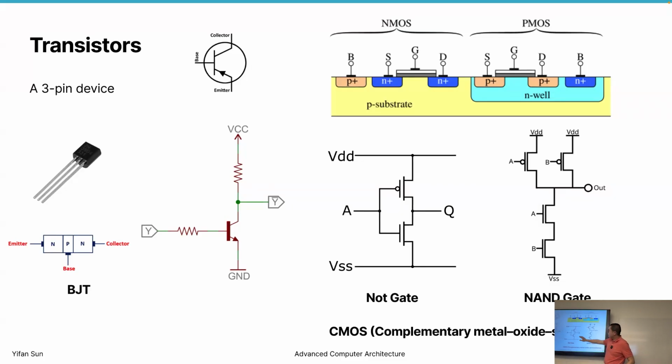So you can consider one side is an NMOS, one side is a PMOS. Don't even need to consider which part is NMOS, which part is PMOS. Just see if there's a circle in terms of circuit annotation. This means kind of a NOT sign. On the input side, that means if it's 0, it's enabled. On this side, if it's 1, then it's enabled. Okay, let's look at what's going on here.